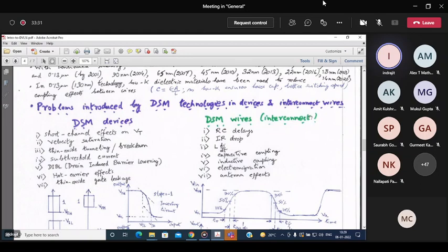And then, as far as the interconnects are concerned, that means the deep submicron wires, they are also with the width coming down, but RC delay, the length is also smaller. But as the interconnect complexity grows, the signal has to travel a long distance from logic unit to logic unit. Then RC delays will need to be talked about. When the RC delay grows, we need to bring in some buffers midway between source and destination. IR drop is also important.